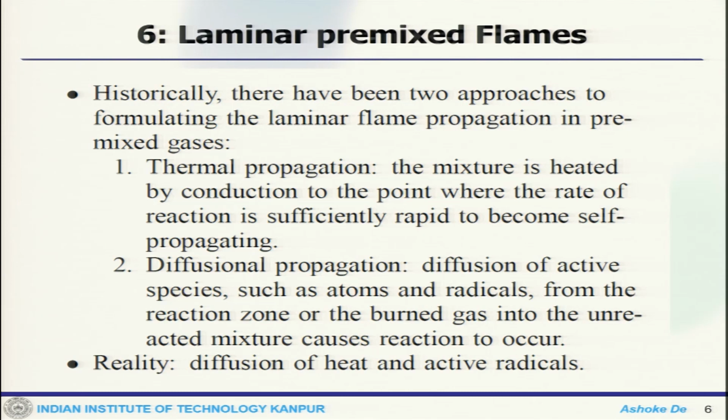Now, to go back a little bit to the history, there are essentially two approaches for formulating the laminar flame propagation in premixed gases. First one is a hypothesis which talks about thermal propagation. That means, the mixture is heated by conduction to the point where the rate of reaction is sufficiently rapid to become self propagating.